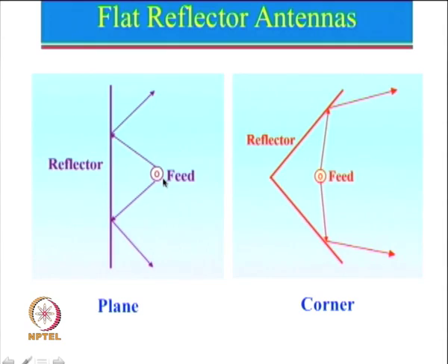However, in case of a Yagi-Uda antenna, if you recall, we had taken one dipole antenna and then behind that dipole antenna we had put another reflector element, and we had mentioned that the reflector element should be greater than the dipole antenna dimension. So, the dipole antenna would radiate something like this, that is the omni pattern, of course directional in this one, and then we put a reflector.